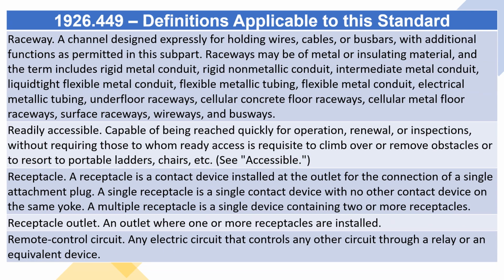Raceway. A channel designed expressly for holding wires, cables, or bus bars, with additional functions as permitted in this subpart. Raceways may be of metal or insulating material, and the term includes rigid metal conduit, rigid non-metallic conduit, intermediate metal conduit, liquid-tight flexible metal conduit, flexible metallic tubing, flexible metal conduit, electrical metallic tubing, underfloor raceways, cellular concrete floor raceways, cellular metal floor raceways, surface raceways, wireways, and busways.